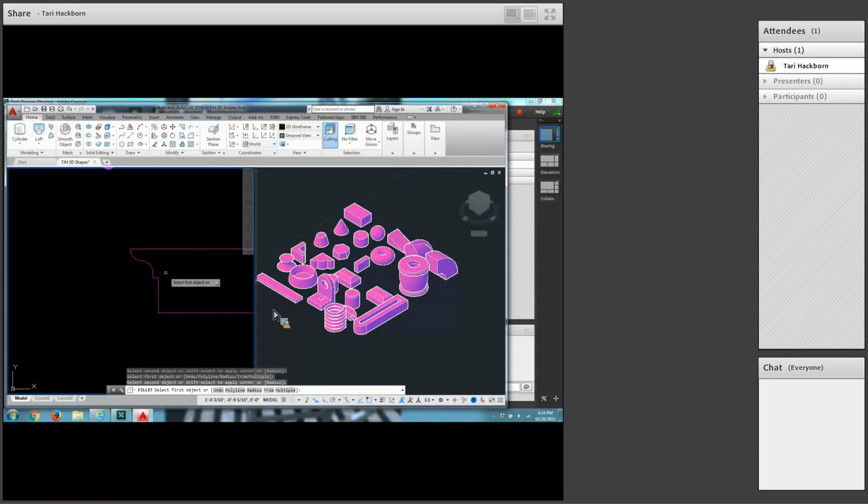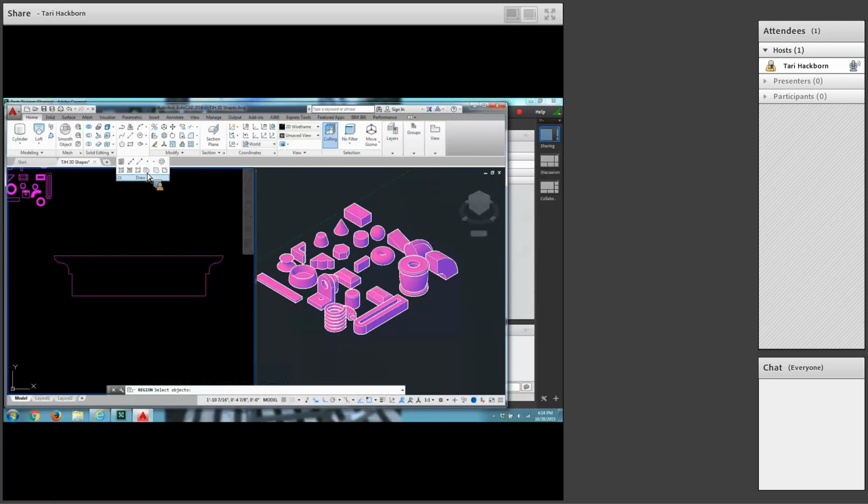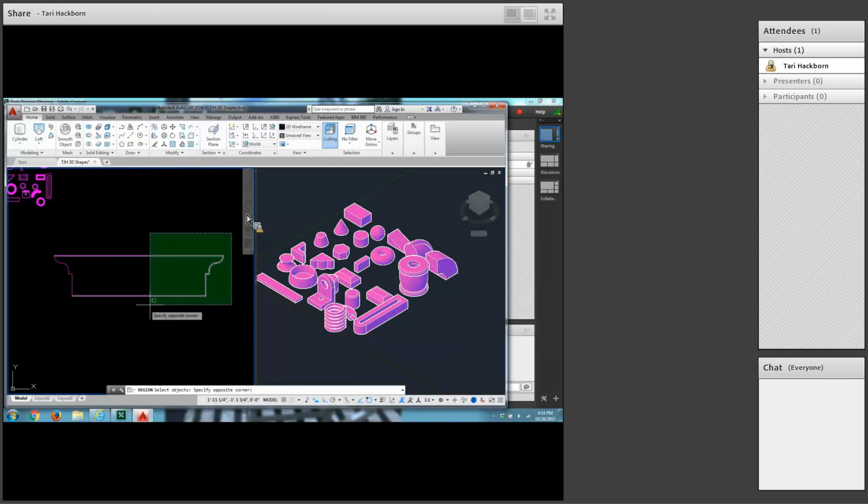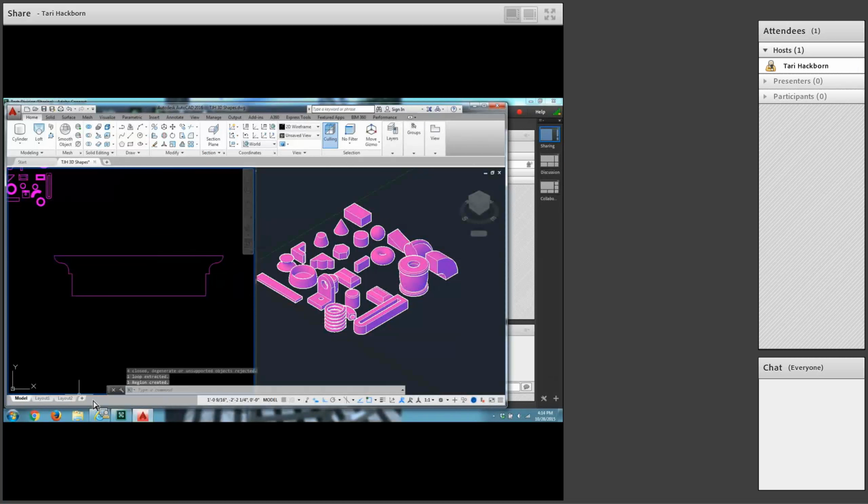Okay. Very nice looking shape. Okay, now the text is starting to talk about polyedit again. So you know I want you to use region. Okay. Draw, region. Select the whole thing with a window. Press enter. It should say 1 region created.